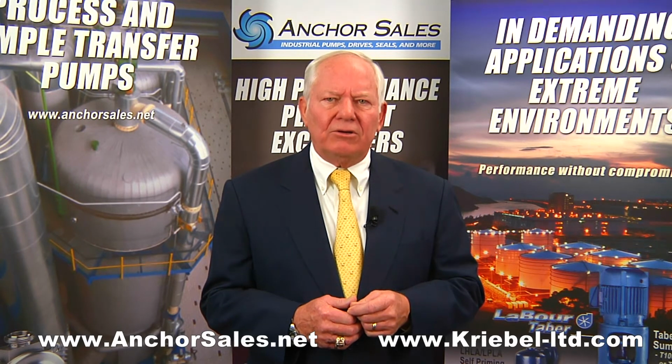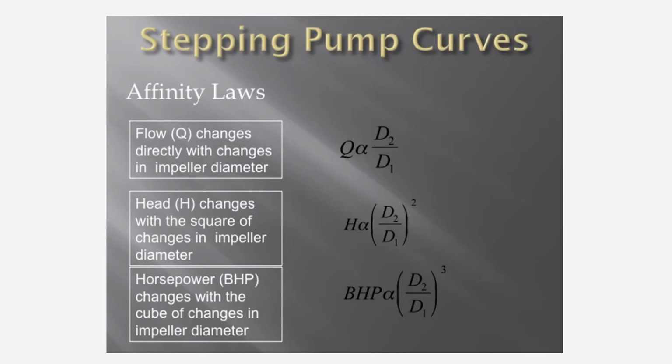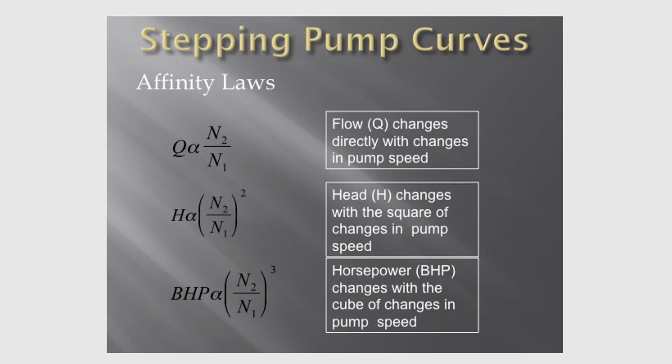Centrifugal pumps follow what are known as the affinity laws. Simply stated, the flow at the new diameter is directly proportional to the change in diameter. The head varies as the square of the change in diameter, and the horsepower as the cube of the change in diameter. The same relationship applies when changing speeds.